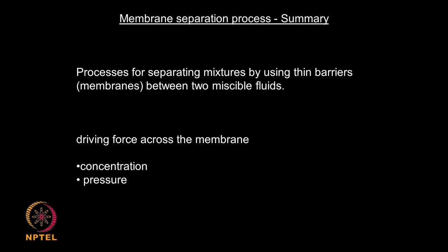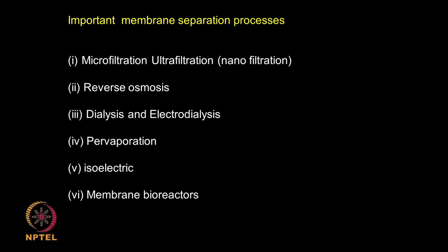So, we have spent a couple of lectures on membrane systems. It is the process of separating mixtures by using thin barriers, polymeric, synthetic or non-synthetic material, between two immiscible fluids. The driving force, although I have said concentration or pressure, can also be voltage and so on. There are a large number of systems: microfiltration, ultrafiltration, nanofiltration, reverse osmosis, dialysis, which is very important in the medical field, electrodialysis, pervaporation, isoelectric focusing, and membrane bioreactors. So, there are a large number of applications for membranes and it is growing day by day.